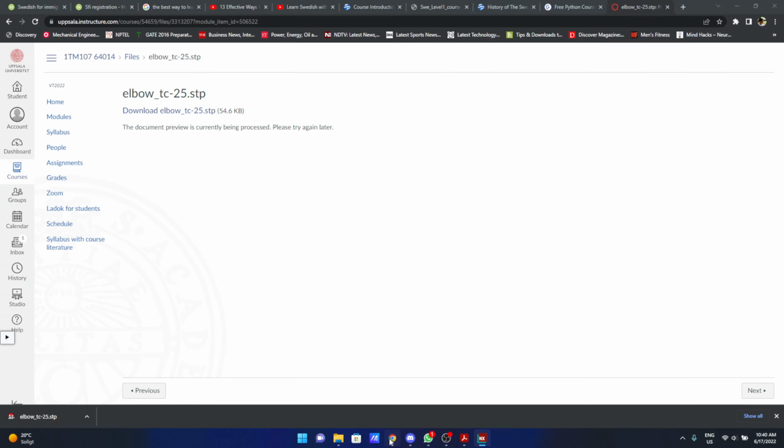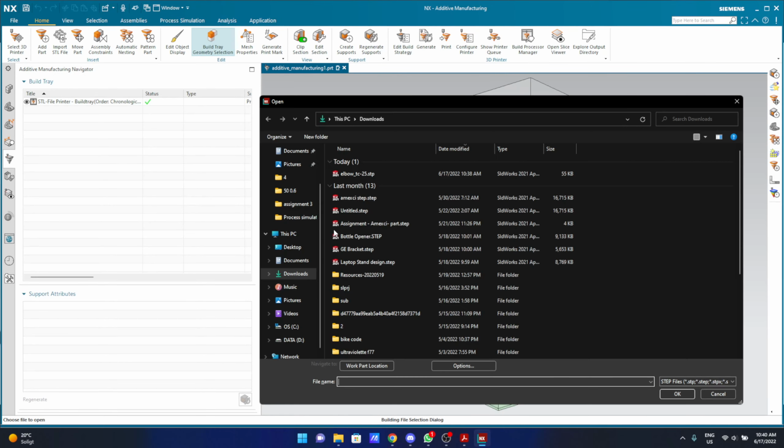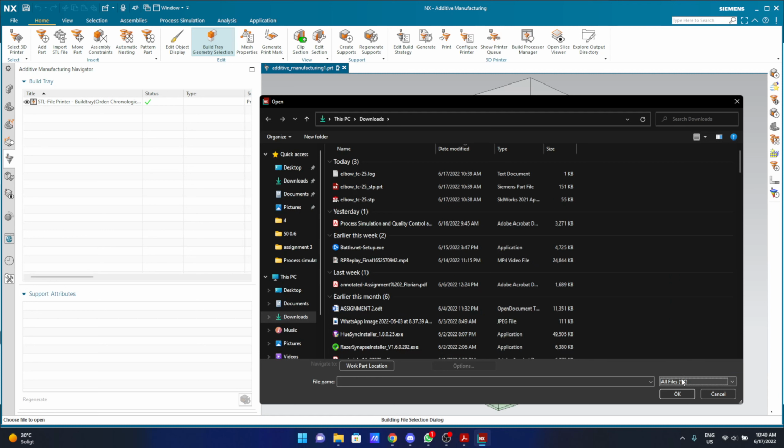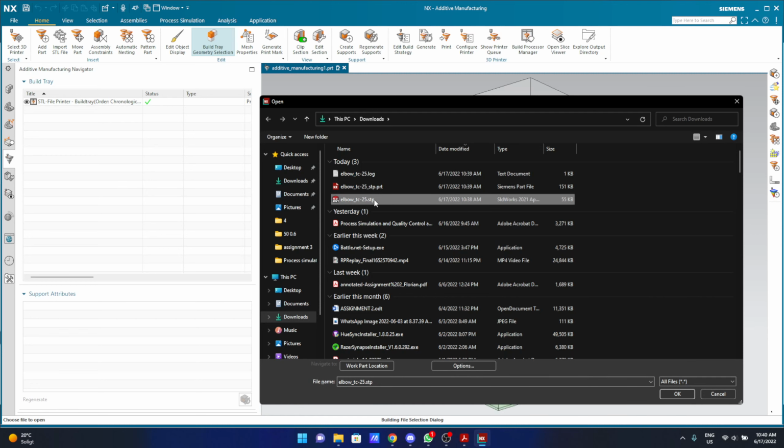I'll just close it up again. You download it from here, and then you open up NX. Control O, go to the place you downloaded the file, switch to all files from here, and this is your STP file.